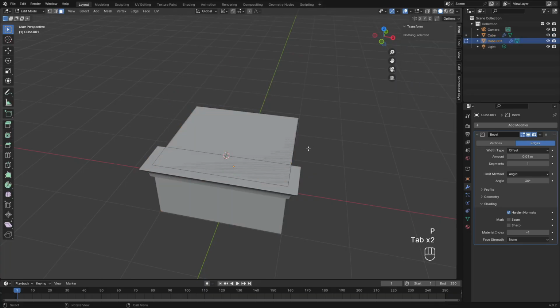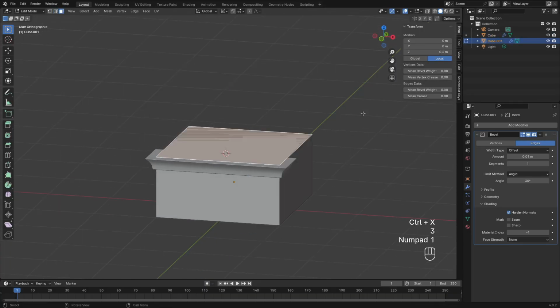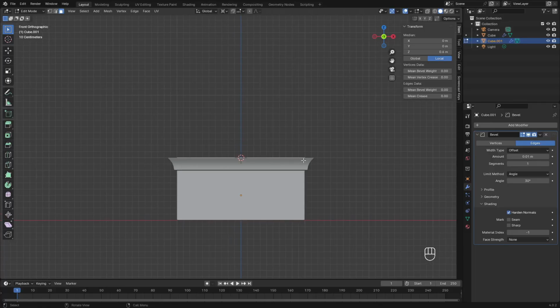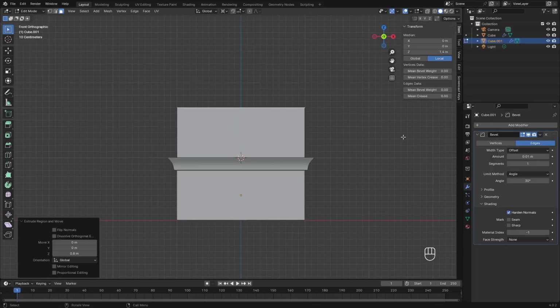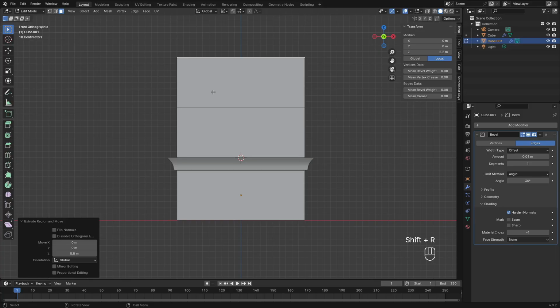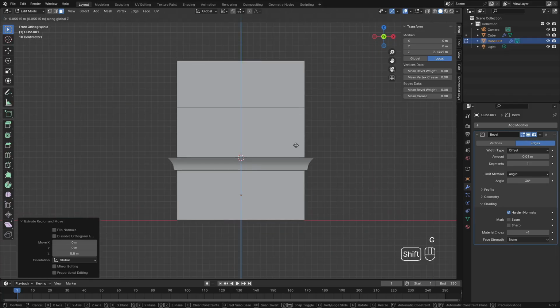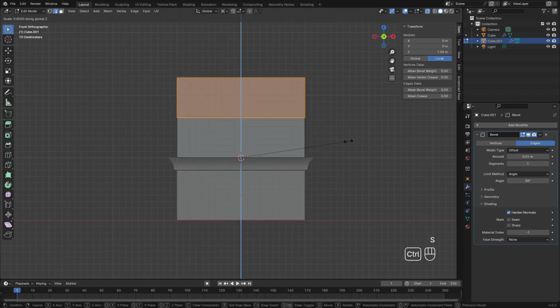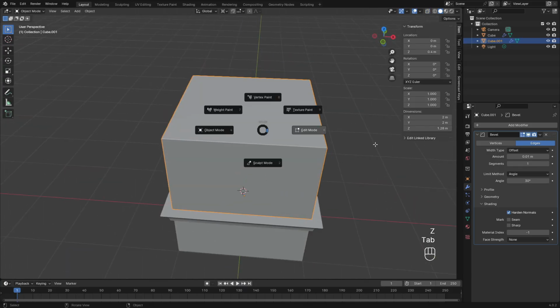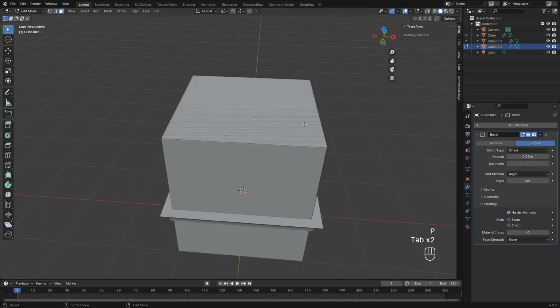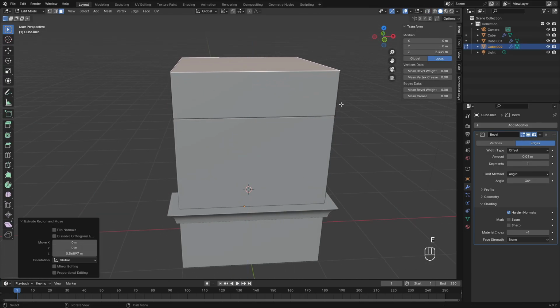For the other two floors, I duplicate the plane of the top of the first floor and extrude it along the z-axis, with almost the same value as the lower floor. Then for the roof part, I duplicate the part from the second floor and extruded it.